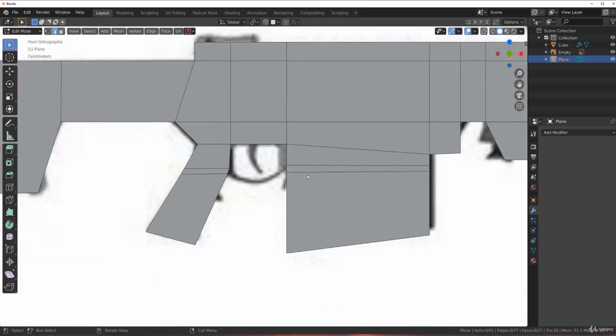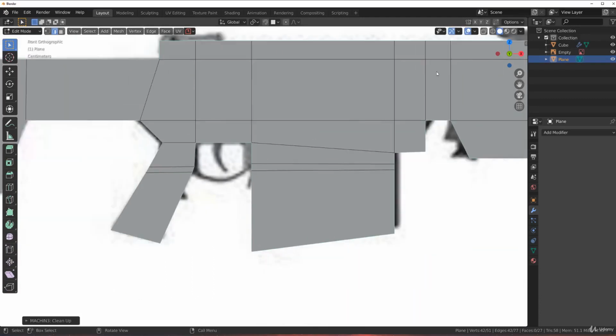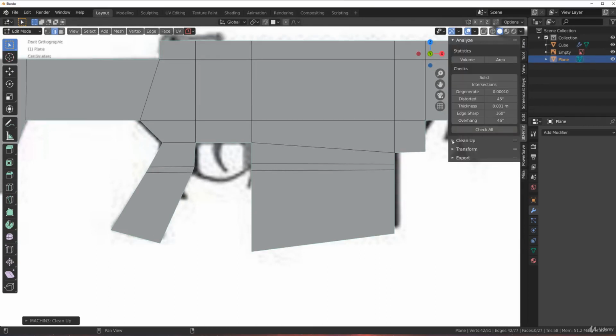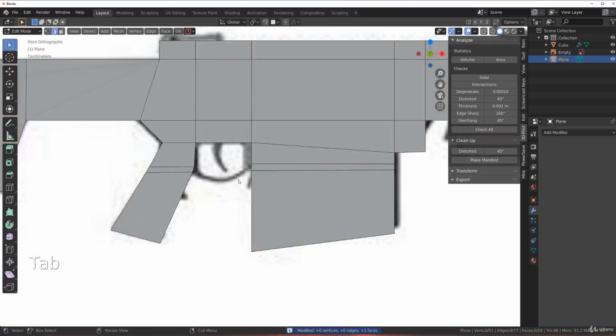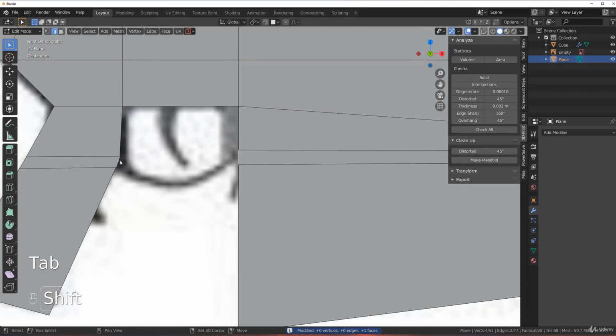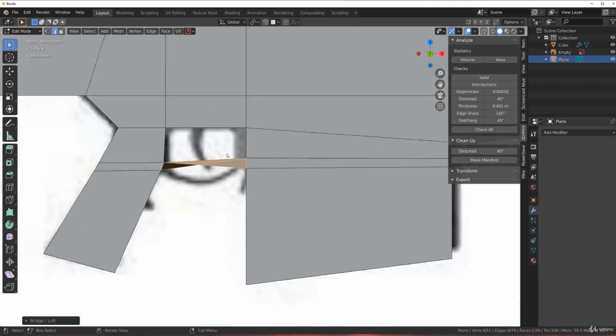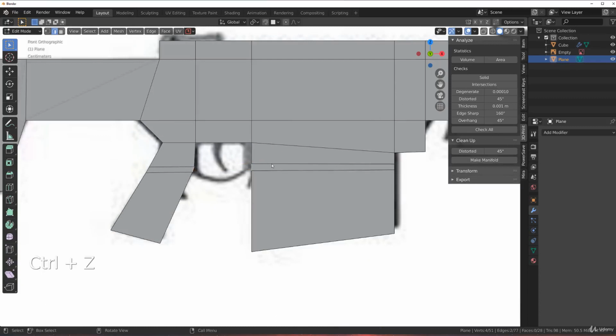Let's clean the mesh. So just press 3 and Machine Tools will clean the mesh. We could actually even run the non-manifold mesh cleanup through our 3D Print Toolbox. So go here and make manifold, and let's see if that's gonna help. Maybe there's some kind of a double edge. Right click and loop tools and bridge, and it doesn't work.